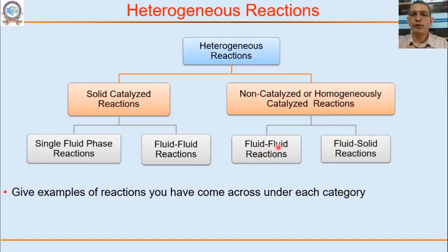Liquid phase is the second fluid phase. But this reaction between carbon dioxide and amine is an acid-base kind of reaction. It is not a catalyzed reaction. So this reaction is happening across two different phases, gas and liquid. Some component from gas reacts with some component in the liquid. The reaction is happening in one of the phases, in this particular case the liquid phase, but it's a non-catalyzed